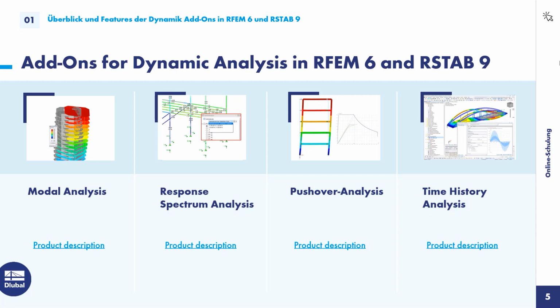Also, the time history analysis is not earthquake only, just as the modal analysis is not. It can be used, for example, for vibration designs and for general investigation of the structure and its behavior. You can also see on the right figure here, in the last webinar, I performed a time history analysis on a footbridge and investigated the acceleration limits.